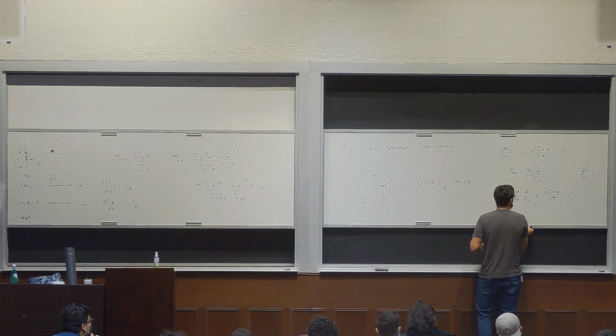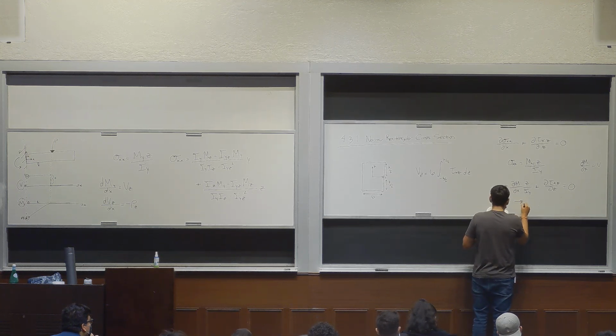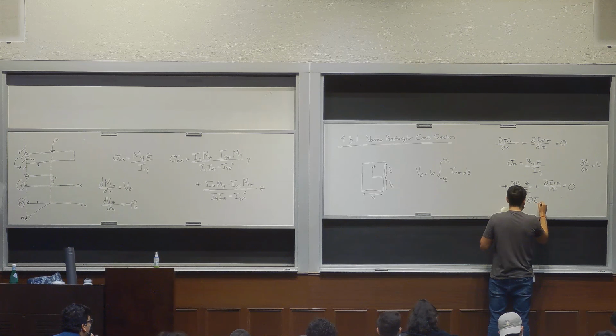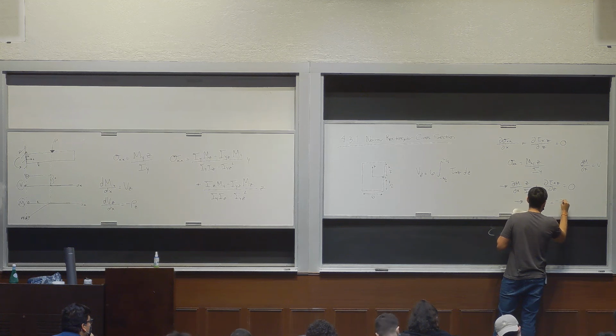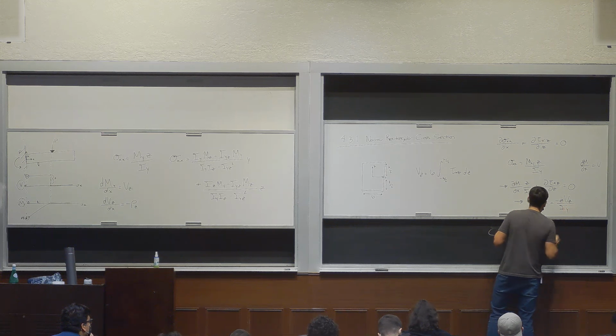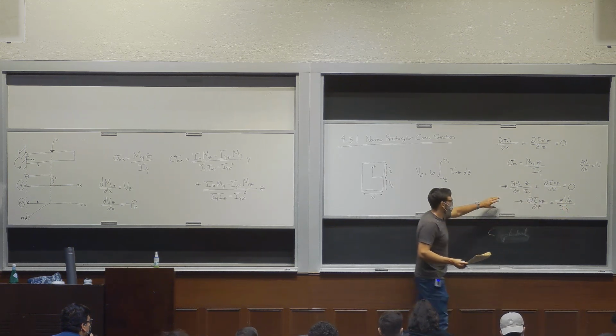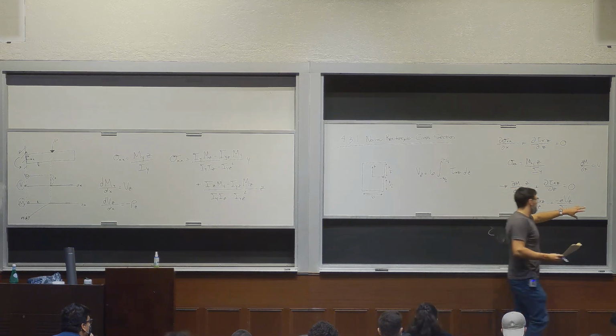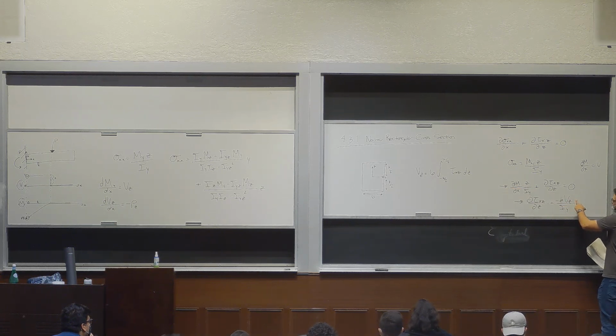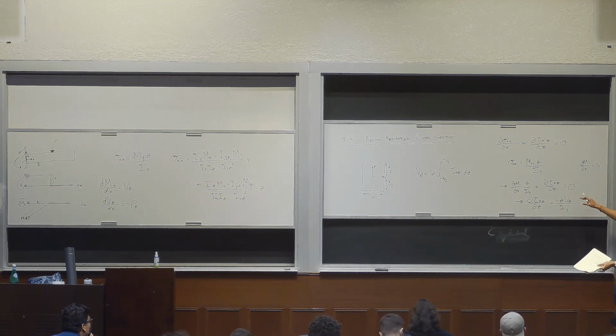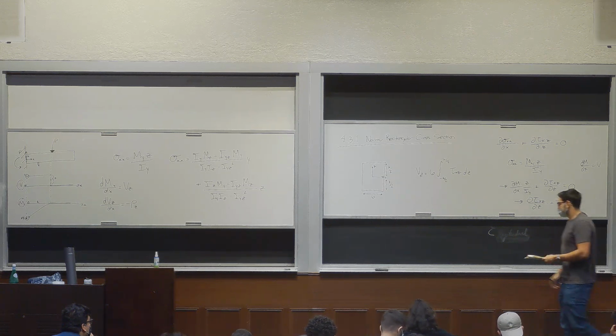And so if we use that relationship, we can rewrite the equation in the following way: d tau xz / dz equals negative z Vz over Iy. So now we have this differential equation that relates Vz to tau xz. And from here, if we integrate this equation, then we can find an equation of tau xz as it relates to the z position. And so that's what we'll do now.